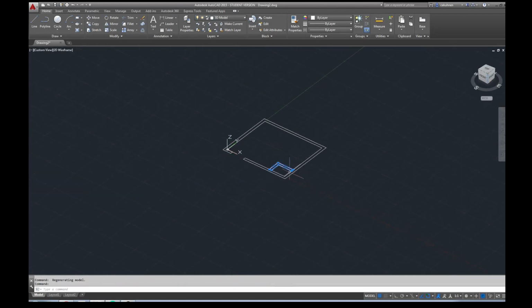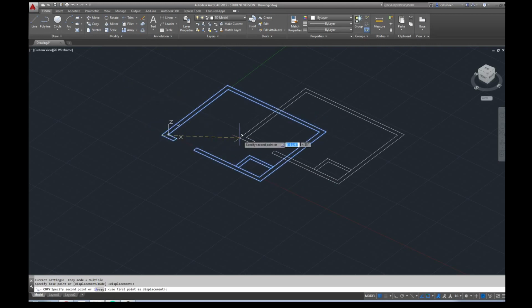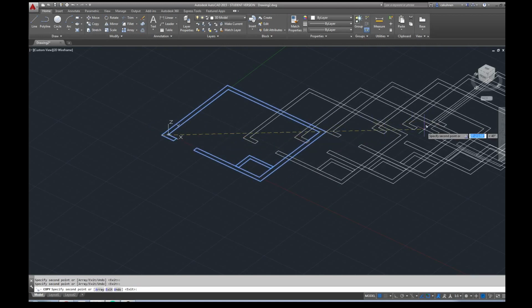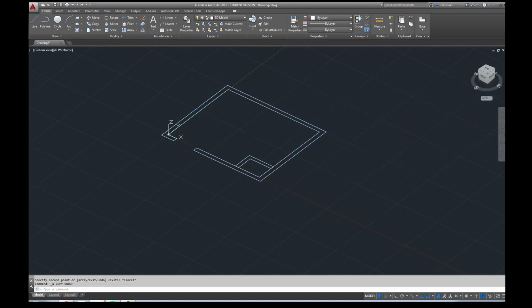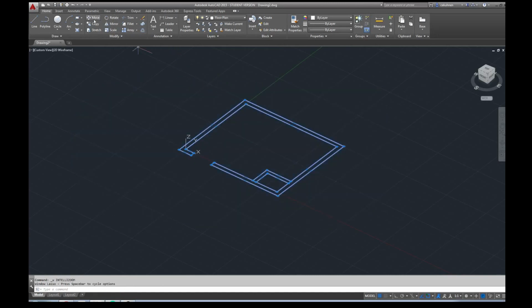Now, those two objects, my interior wall and my outside wall, I'm going to copy. So, for example, I click copy and then it asks me about a reference point, which means, for example, from this point, make a copy to there, there, there. See, wherever I click after the first time, it creates a new copy. But what I simply want is to make a copy and leave it where it is. So I click copy and I simply could enter 0, tab 0 for the scene center. You see where the yellow line comes from, and then type 0, tab 0 to simply place it where it